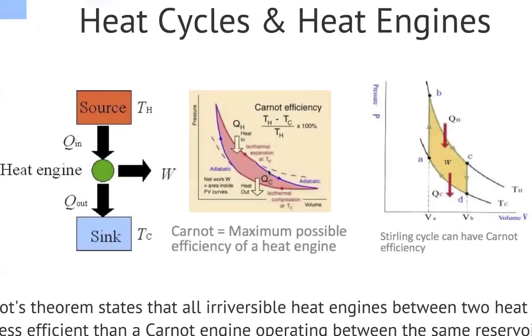So of course the temperature has changed because now you're in the cold part, okay? So it's at TC right here at this point, which is the cold part. Then you have isothermal compression. So for instance, the piston is pushing in and compressing the gas. As you compress, the volume decreases, so the curve goes down like that. Okay, again at a fixed temperature.